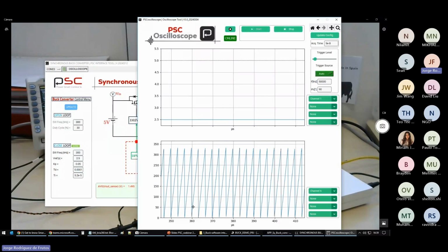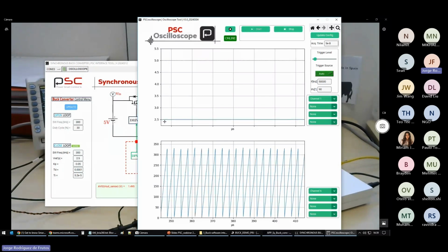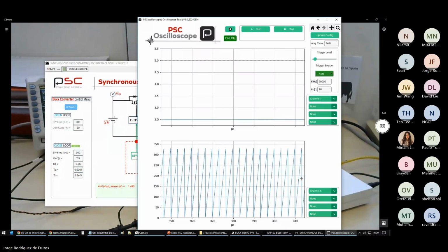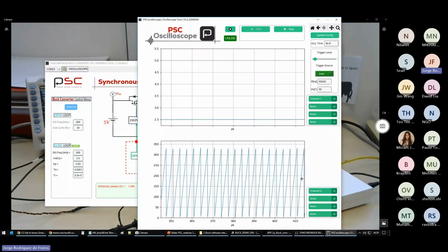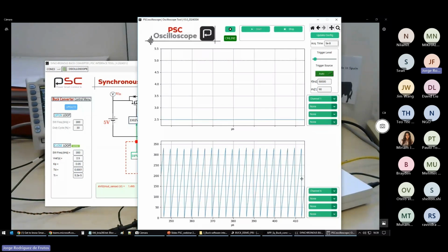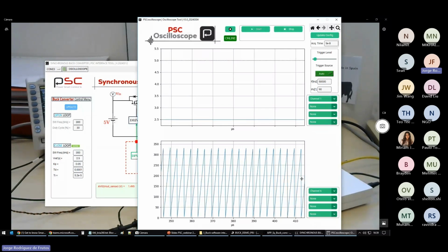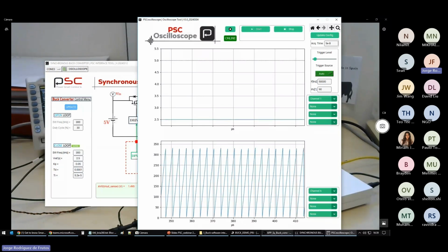This waveform, which is the output voltage, and the waveform we had before, which is the current across the inductor, are signals which are sampled by an ADC and then measured with the embedded oscilloscope in Vivado. This signal is used directly from Vivado.